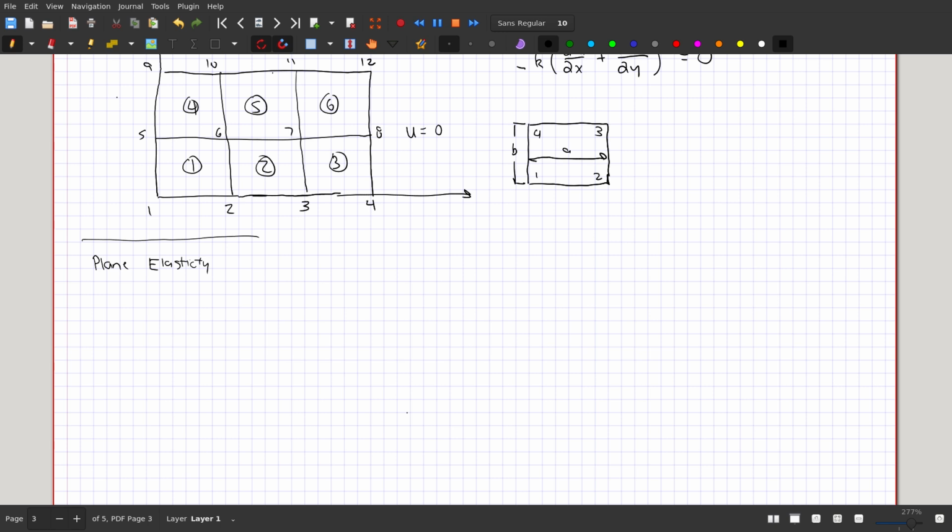And the other one is plane strain. So plane strain is when you have a very thick through-the-thickness specimen. So you're solving something in the plane, but you have a very thick specimen. Remember, strain is like change in length over length. Well, if the change in length is small and the length is big, then effectively that strain is zero, right? So plane strain would be that problem.